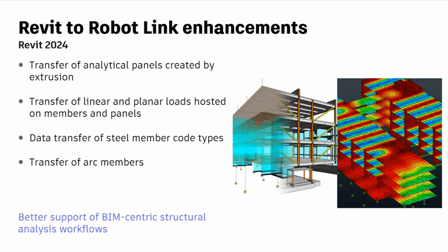Revit and Robot Structural Analysis. There are Revit to Robot link enhancements. Revit is recommended as the central for the physical and analytical model coordination, and its analytical model geometry can be accurate and fully versatile. The nature of the whole Revit Robot interoperability is being adjusted. We now truly have a bidirectional geometrical exchange that's focused on the analytical model and its material and sectional properties. And the analytical driven modeling approach for Revit introduces new enhanced structural modeling capabilities for analytical modeling.